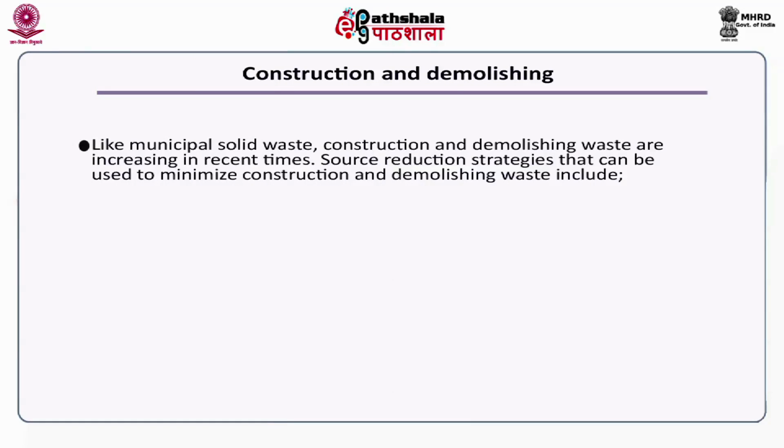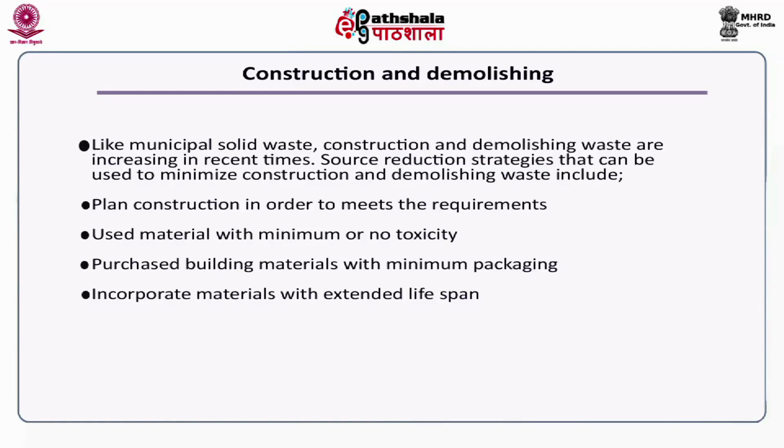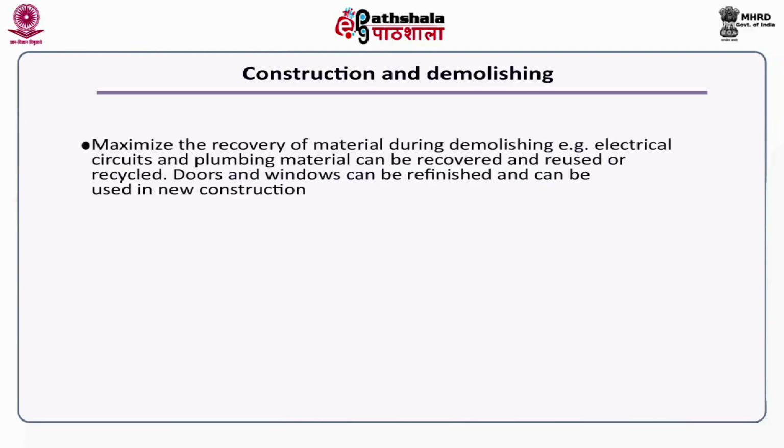Now, let us discuss some of the source reduction strategies at a construction and demolition site. Like any other municipal solid waste, construction and demolition waste are increasing in recent times. Some of the source reduction strategies are that you can minimize the construction and demolition waste by planning a construction in order to meet the requirement, then use those materials with minimum or no toxicity. You can purchase building materials with minimum packaging material and incorporate those materials which have an extended lifespan. Also you can use reusable products.